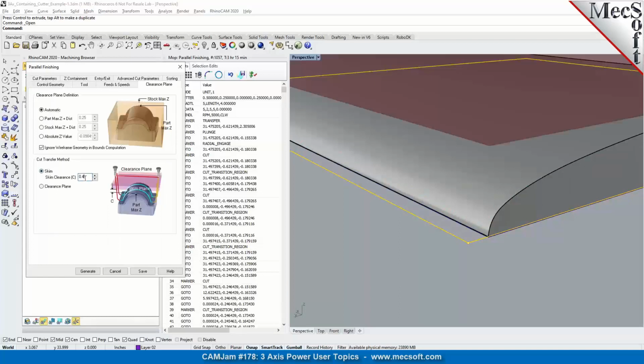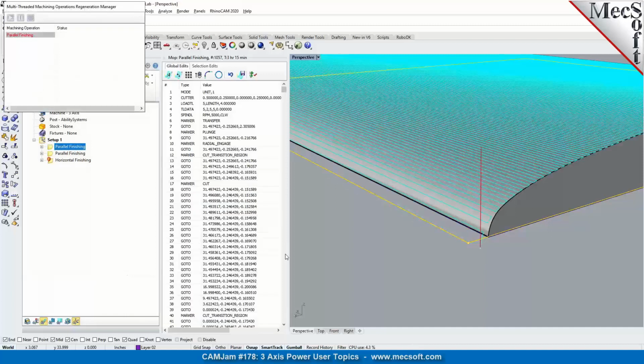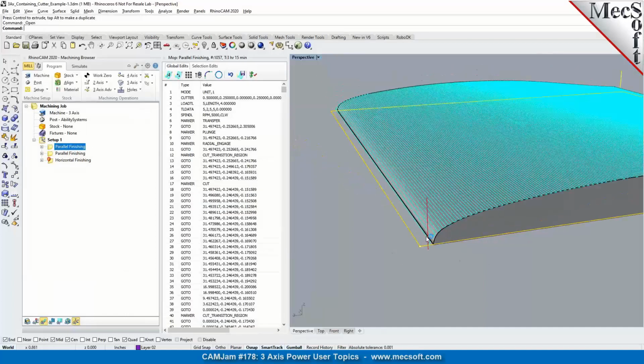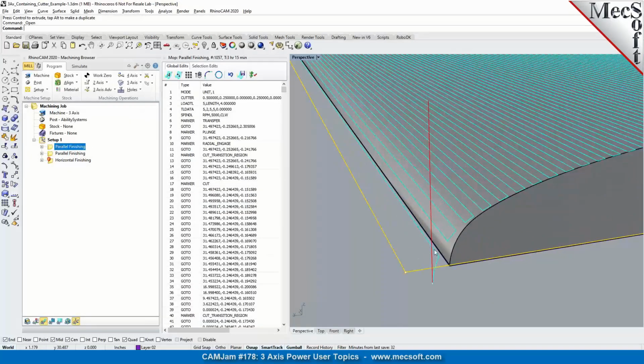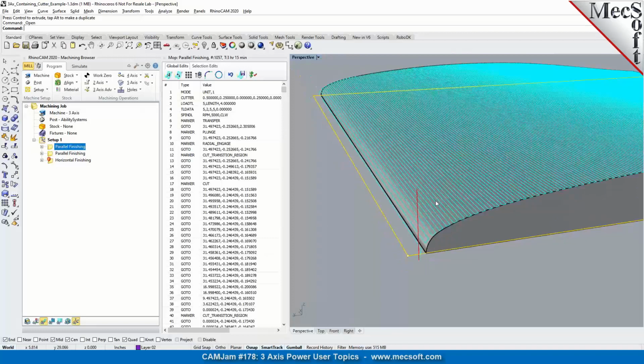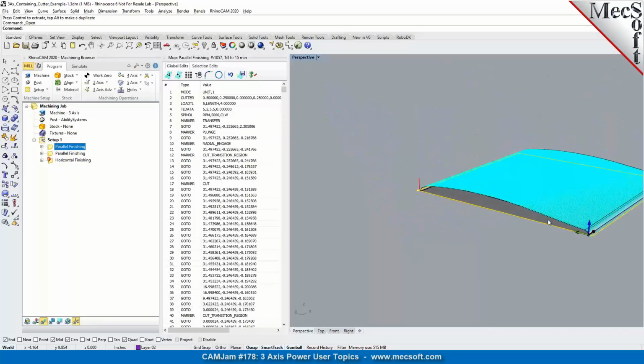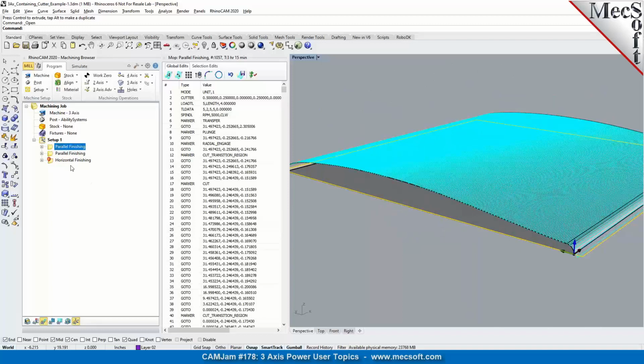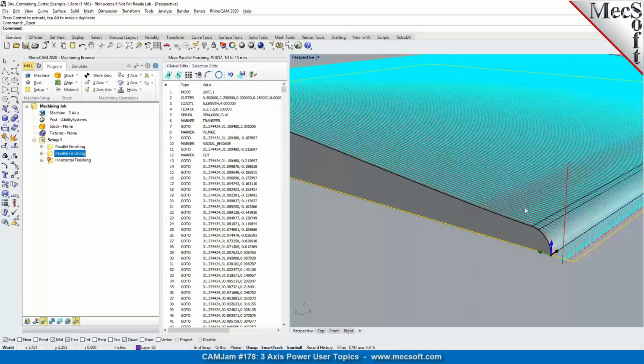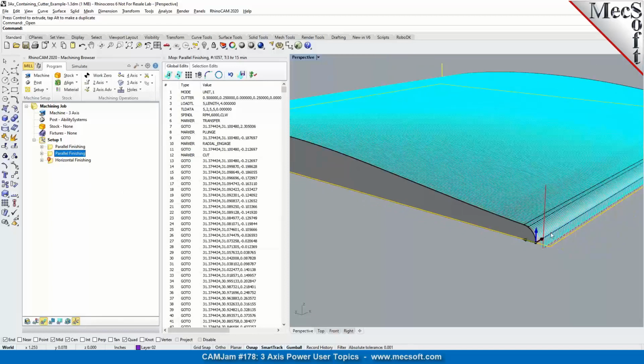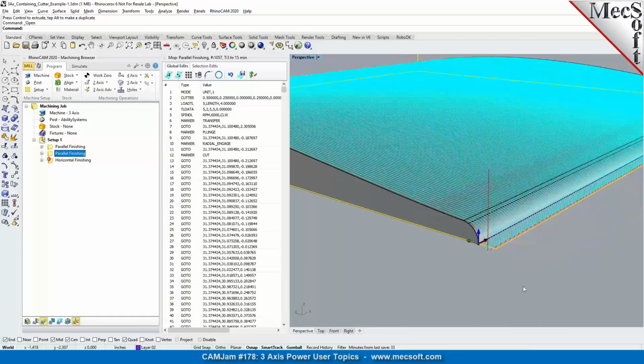So the same thing can also be set whether you're cutting along 0 or across. In this particular case, you wouldn't have much effect on the skim clearance because you're going parallel to the x-axis, which the angle of cut is set to 0. You'll see the effect more when you're cutting across as you're riding down the fillet or the radius in here.